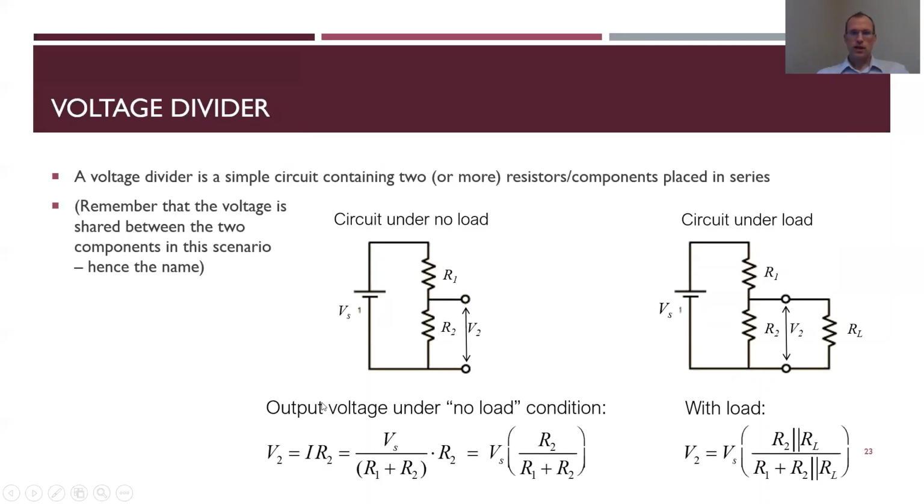So looking at this, the voltage across R2 is sometimes called the output voltage, because sometimes we attach some other part of the circuit to this. Like here, I've attached a new resistor to it. So R2 is my output voltage. I basically put R1 here to control my output voltage. So I have some voltage Vs from a battery, but I don't want all that voltage going to this resistor RL over here.